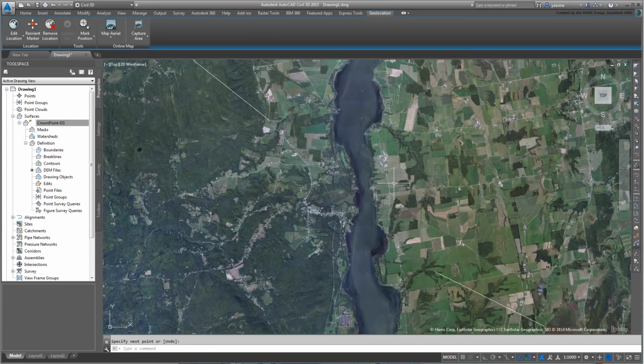Now create a rectangle by snapping to those 2 reference points. If your object snaps are not active, use the F3 toggle. Delete the 2 lines when done.